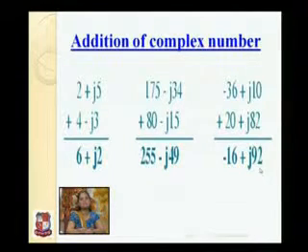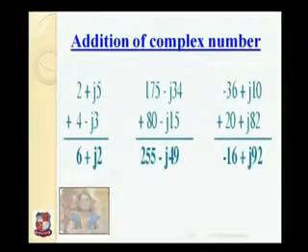So using this method, you can make the addition of two vectors, and if you have to convert it into polar form, you can easily convert into polar form using the given equation. Find the magnitude of resultant and then find the phase angle of resultant. So it will give you the vector in a polar form. Now we will discuss subtraction of complex quantities.